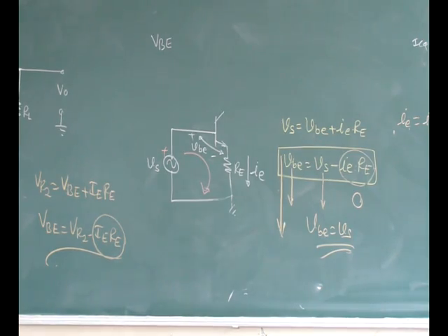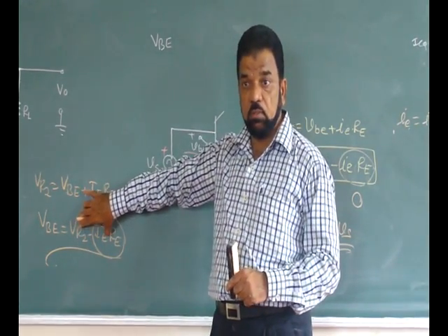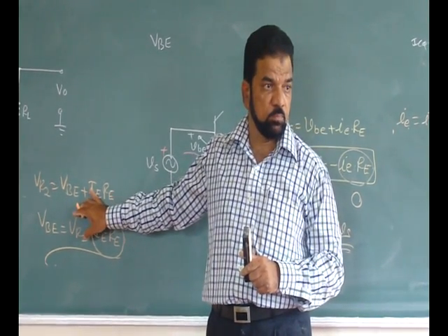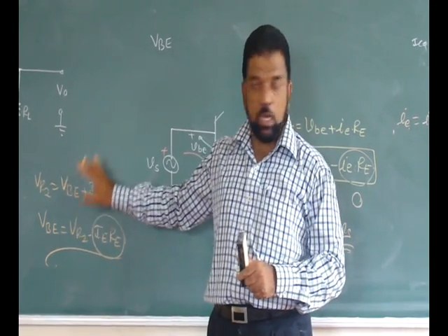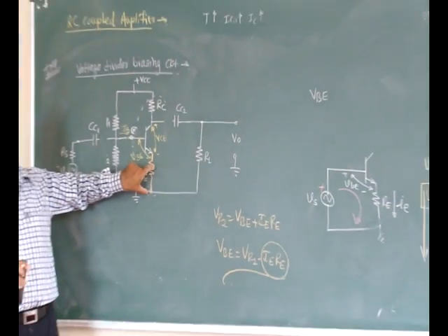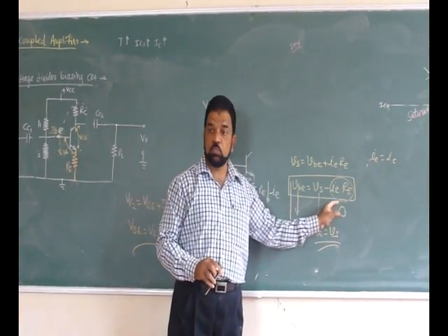Okay. So can I have the DC voltage there, and can I make the AC voltage drop across RE equal to 0? I will repeat. I want the DC voltage across it, so I will use this RE as it was. But whatever the AC voltage across this is, what do I have to do? Make it 0. Because ultimately this is the AC voltage.